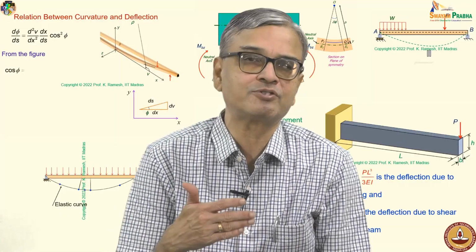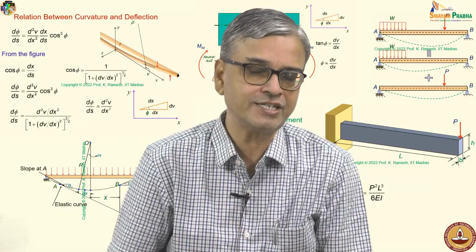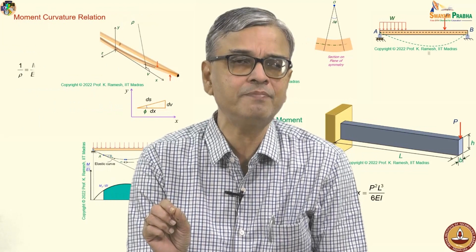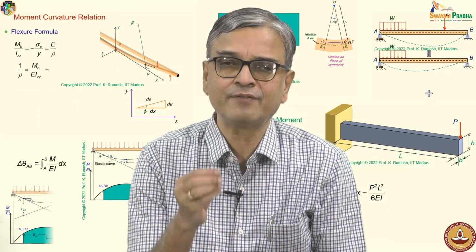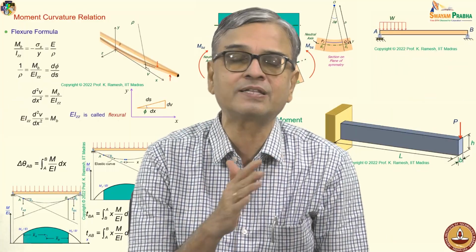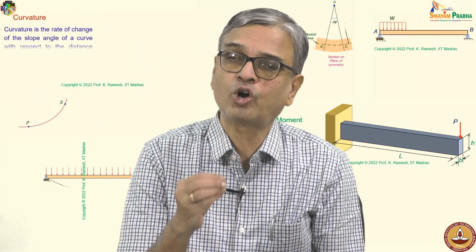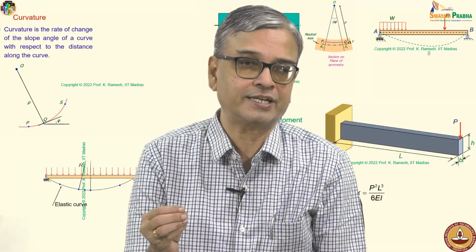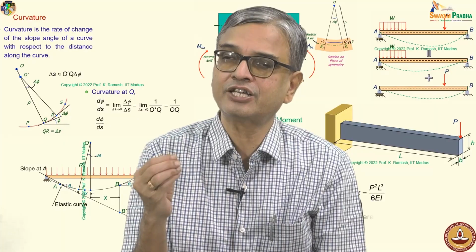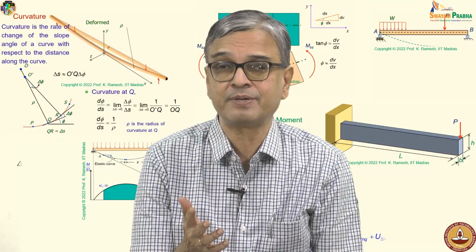People also have developed singularity integrals, which we are not going to look into, because it becomes a mathematical exercise. If you are able to write one single equation for the entire length of the beam, the equation is valid and we have followed a sign convention, you get the slope and deflection as per the sign convention without any difficulty. The same thing applies also for using the load deflection equation and then doing the integration. And I said the load deflection equation which I have given is also valid for statically indeterminate beams.